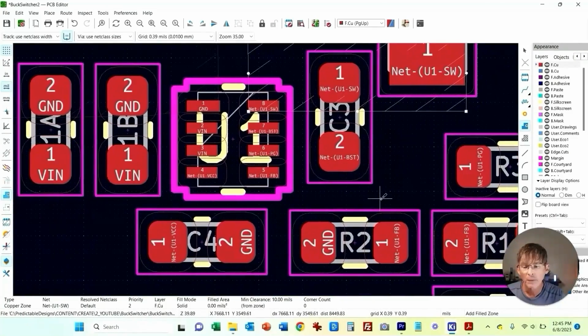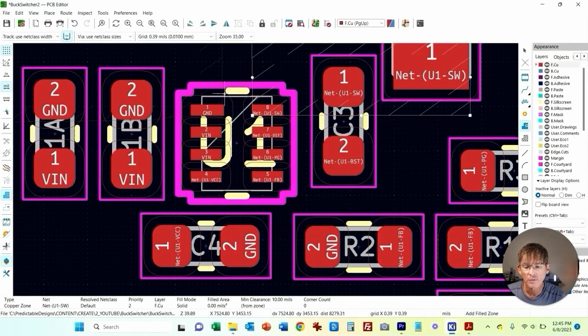Yeah, probably what I'm going to do instead of necessarily a copper pour through here, you could just, because even C4, these are all fairly low current, so it doesn't really have to be super wide. So we'll just see what the widest trace we can get there, and we'll just tie it from the ground pin here, and then we'll just route down to here.